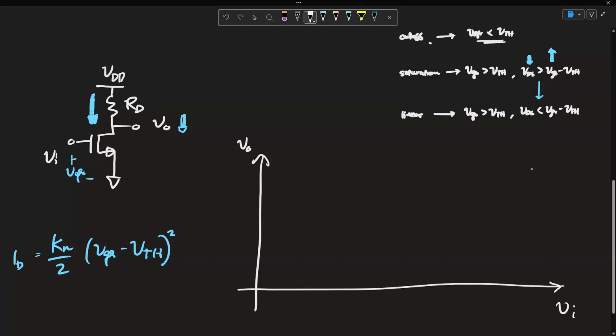So we're going to expect a few things, right? We have a threshold voltage, before which, VI is VGS, by the way. We know that from this, no? VI is VGS. So we're waiting for VGS to be greater than VTH in order to escape cutoff. And then it successfully escapes cutoff, and goes into, of course, saturation.